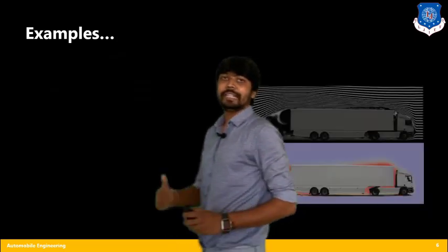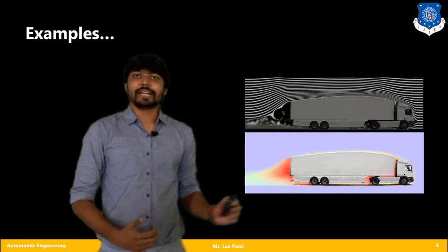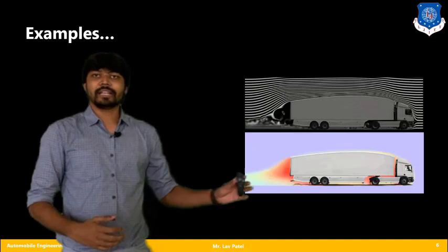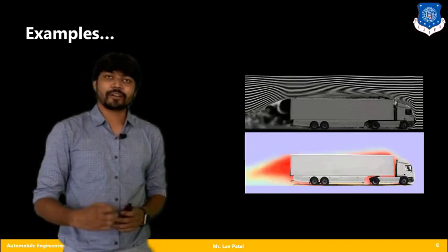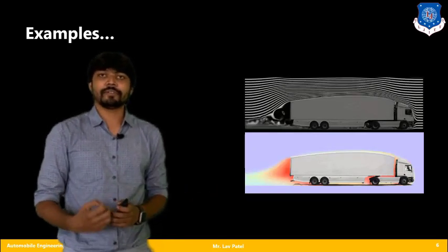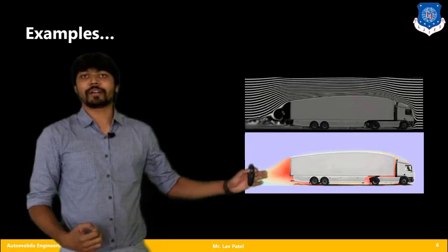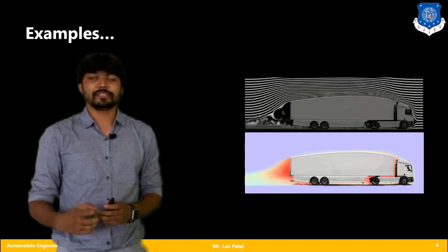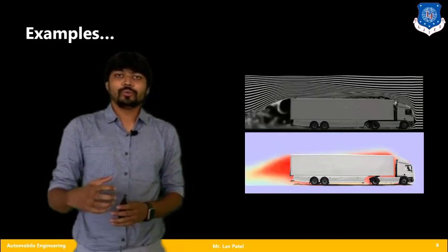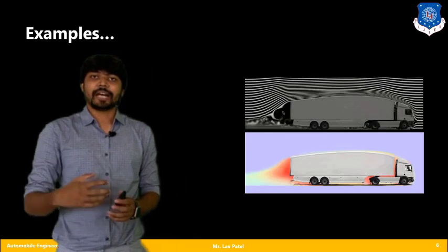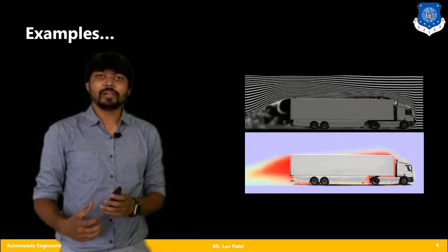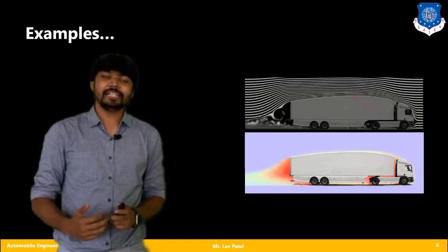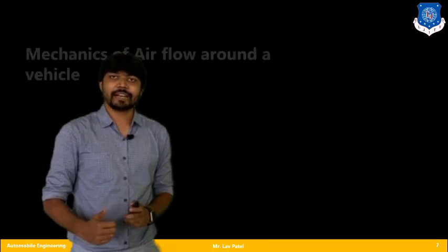While we are talking about the second type of vehicle, that is the truck, you will see there are lots of changes in the aerodynamics, or we can say the flow of air. Here you will find a number of vortices, and the pressure differences at several points change. So we have to keep in mind that to deal with maximum speed I have to optimize the different shapes of the vehicle or different components of the vehicle to minimize the drag or the air resistance.